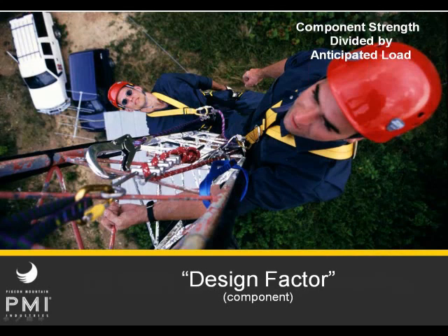Sometimes this information will be dictated by the company or agency or the authority having jurisdiction that you're working under. But if this isn't the case in your situation, you might be tempted to select a design load factor as a starting point. That is, how much load do you expect to put on the rope, and how much stronger than that do you want your rope to be? Keep in mind, though, that the component design factor is not the same thing as a safety factor.